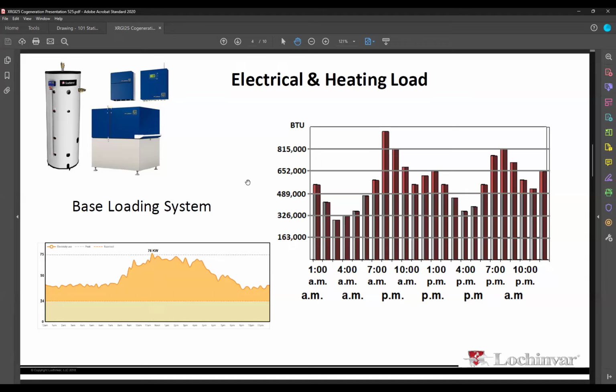If you take gas, something that's more than 50% of the grid composition, rather than having the generation losses through the stack and all the thermal losses and distribution losses, what if you had them at the building? So not only are you producing power for the building at 24 kW, but you're also producing about 160 MBH. And a lot of the buildings that I designed, I think 11 systems, each one of those systems, on average, including the maintenance, was about $20,000 to $24,000 a year in savings.